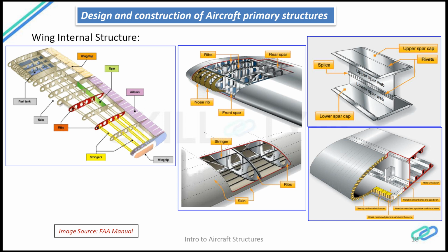Even within the 2D elements, sometimes for the web they will use only the shear element. That means it takes only the shear, it doesn't take any bending. The bending is primarily taken up by the flanges or the bar elements or the rod elements, which is the couple, tension and compression, equal and opposite couple, that will be taken up by the rod elements.